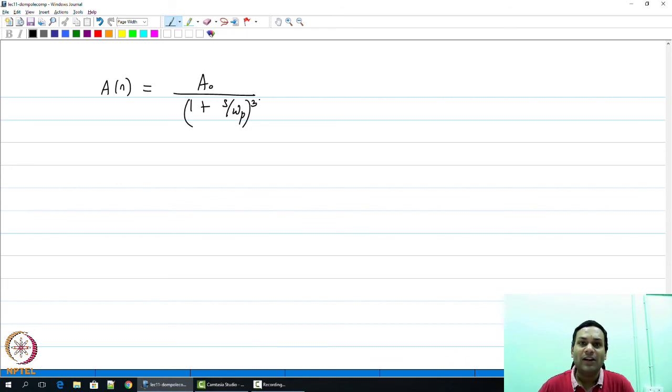I now need to find out where to place omega d. The way I'm going to do it now as an example is I'm going to place omega d at some frequency much smaller than omega p, and figure out how large a0 f can be so that the system is stable. So let us quickly look at this.